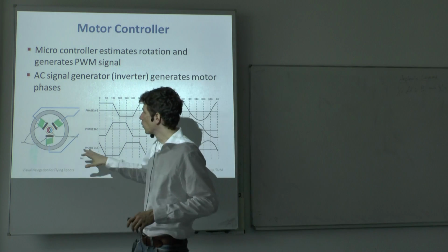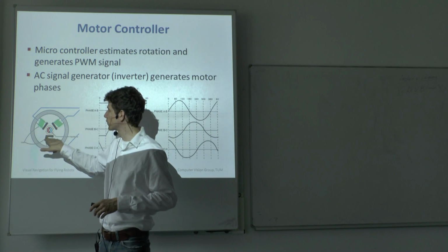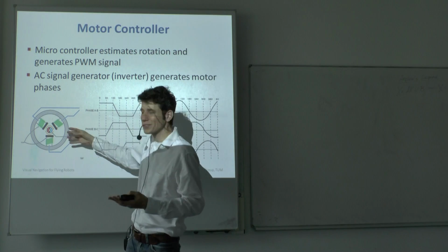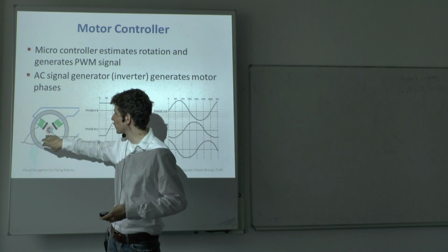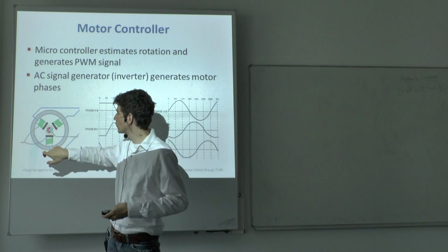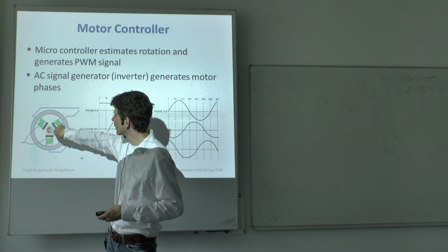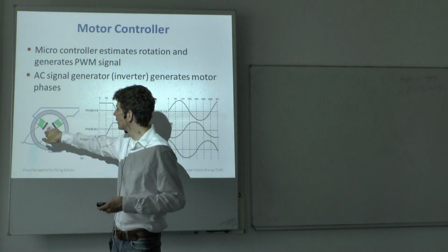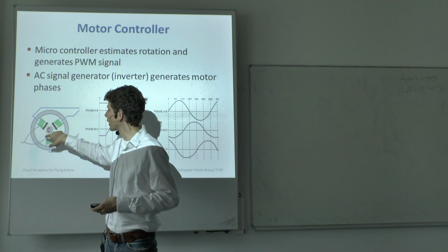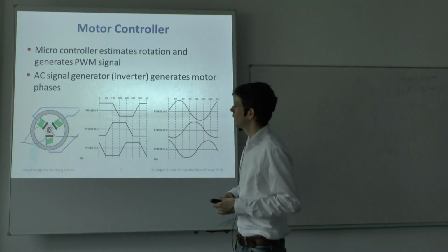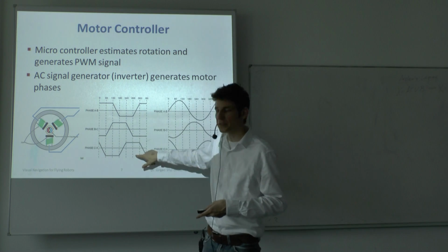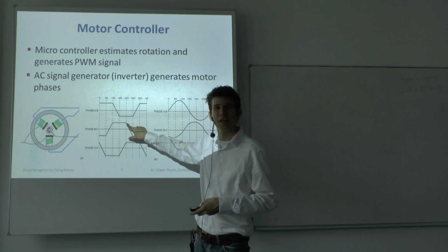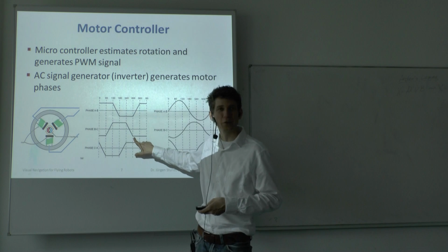So in the easiest case, a motor only has 3 coils, and you have a permanent magnet on the inside. So it's quite similar to this DC motor. You switch on a certain voltage, it will turn, and then you move around this electric field or the magnetic field induced by the electromagnets to make the rotor turn. And then these phases can look like this. This is a very simple pattern where you just have either full voltage or a linearly decreasing voltage.